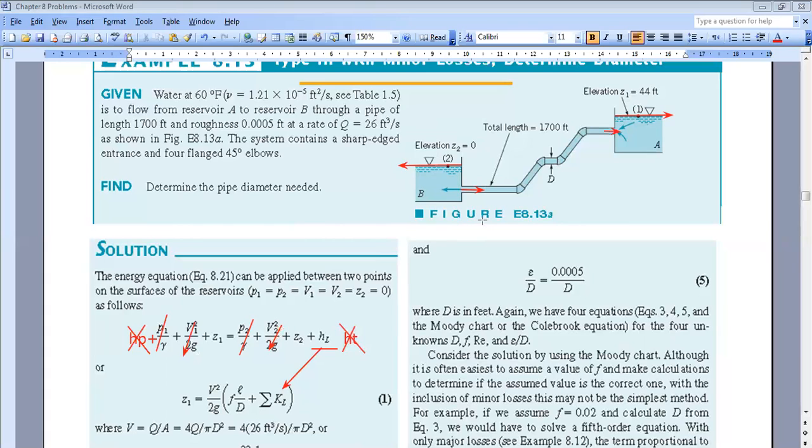Now, the velocity inside this duct is not zero, but is the same everywhere. Since you have the same cross-sectional area, the velocity will be the same everywhere. Then this is the average that you want to compute. So here V is to be found. Why don't we know it here? Because the diameter is not given. The question is to calculate the corresponding diameter needed. Here Q is given. Since Q is given, I can relate the velocity and the diameter through the relation of volumetric flow rate.